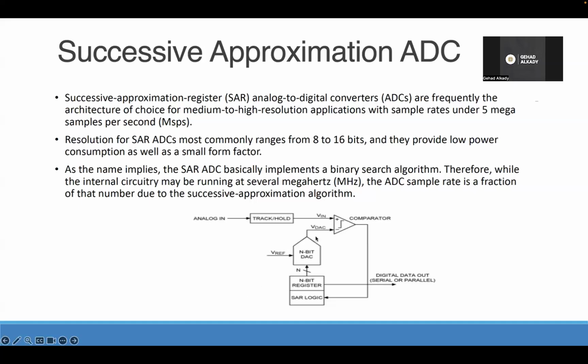What I explained is at the beginning of the ADC's operation. Then, with an input of 1 at bit n over 2, the SAR logic block will determine that the input voltage value lies in the upper half of the original voltage range, which is from Vref over 2 to Vref, for the new iteration.